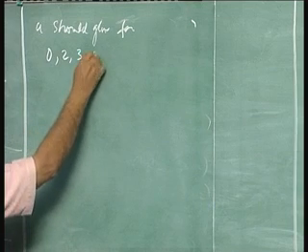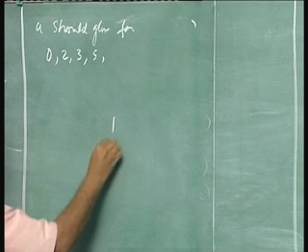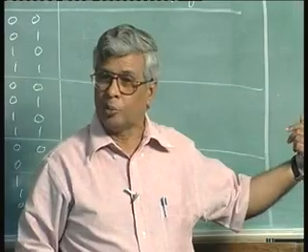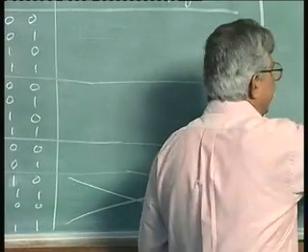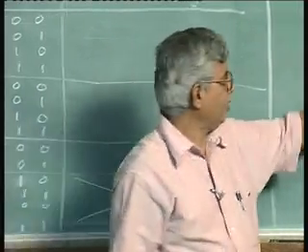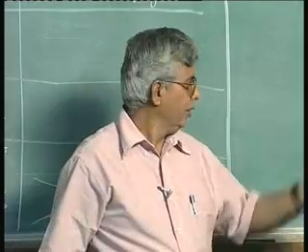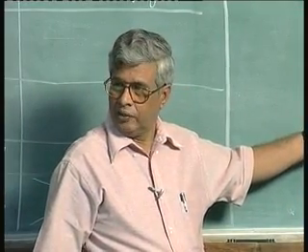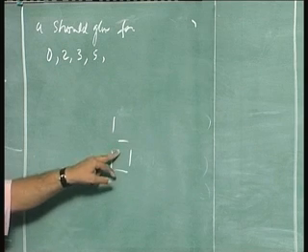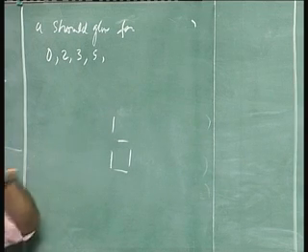5? 6? 6 depends on how you define 6. We will have 6 like this. If you also have alphanumeric characters, then this will be used as a small b. In that case, I would put 6 like this. If I am only doing numerals, I can have 6 like this also, right? This may be considered as a small b, so you can put a cap on the top. So to make it simple, I will have 6 of this type. So A will not glow for 6.